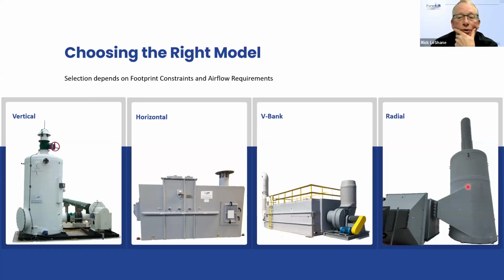The neighboring community has a height restriction on the equipment used at the wastewater treatment plant, so the neighboring community doesn't see the treatment plant. The radial flow units do a great job, but they are a lot taller than our lower profile VTS system. So the VTS just makes more sense in this situation.